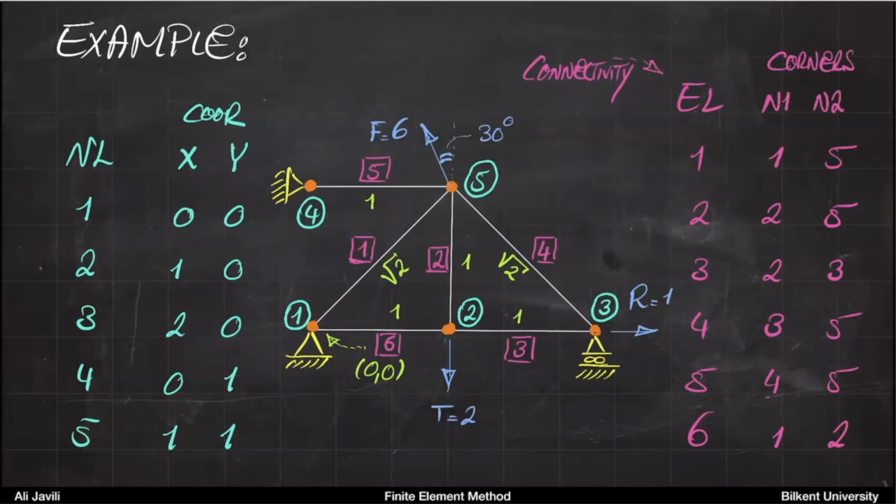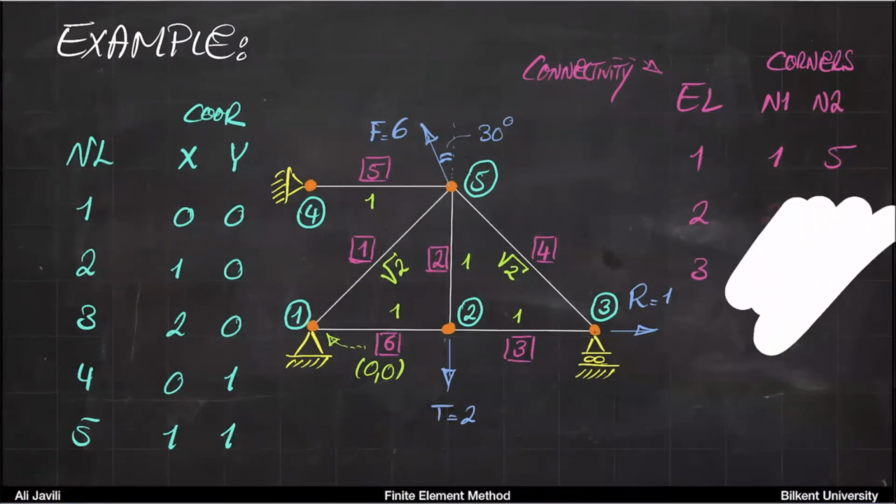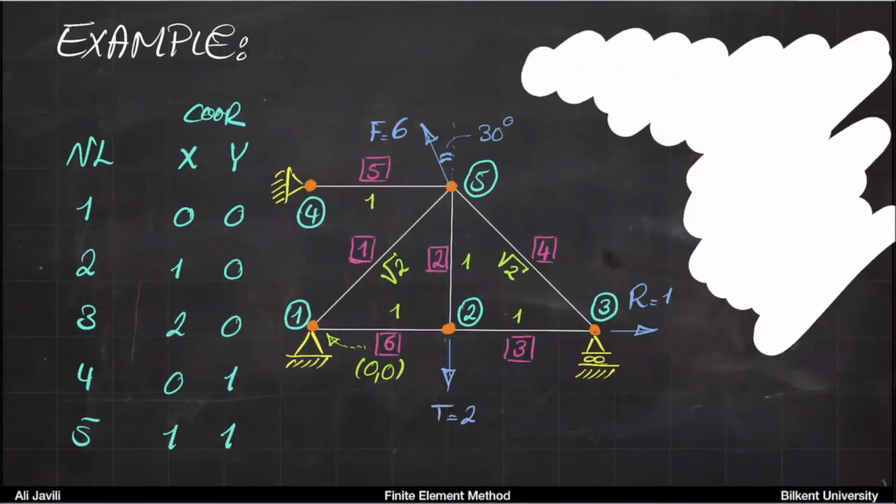All right. And then again, the importance of the element list, maybe you cannot exactly appreciate it now when you do these type of problems on paper, but later when you want to actually program it and run your code, you usually have this loop over the elements, and elements should know its nodes. So later you can appreciate why we do this when you program it. I mean, visually you already see the connectivities, so it's rather trivial to just observe it. Okay, so I'm going to remove this and create the extended node list.